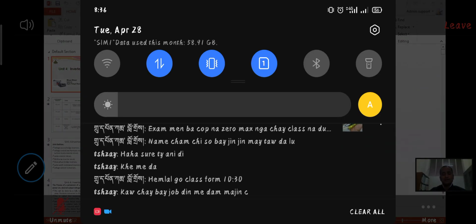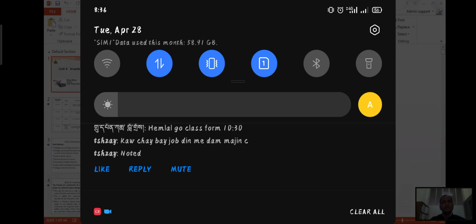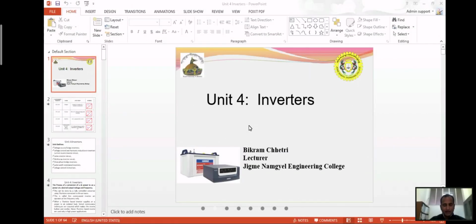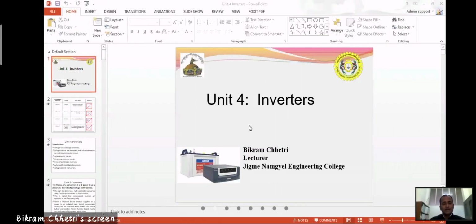And the other one is a hybrid system. If you see in our AGM block, we have a hybrid system. We have a charge controller which is a hybrid. It is connected both to the solar panel as well as to the grid, so the battery can be charged from both ends. If there is bright sunshine, it will charge directly from the solar panel, the photovoltaic cell. If it is a cloudy day and the battery is going lower than expected, it can directly charge from the grid connected system. These are some of the hybrid systems which are practically used.